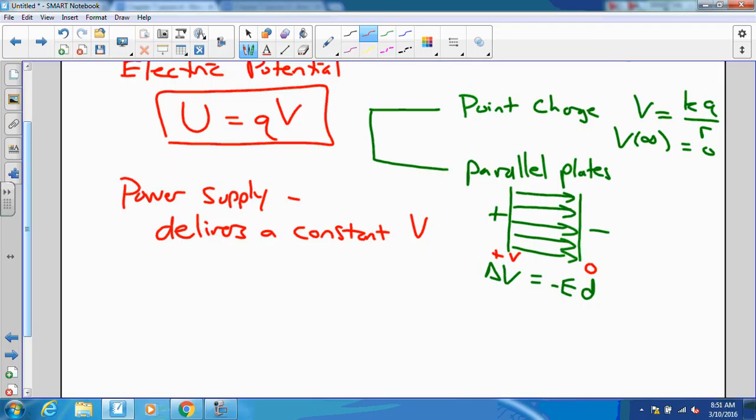This voltmeter is not delivering on its promise. It's supposed to be measuring 20 DC volts, and instead you can see that it's providing a conduit straight through for the current, and you can see that because notice that my power supply here turns off. Let's try the analog instead, see if it does any better.